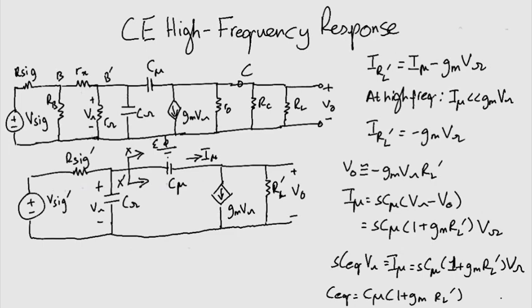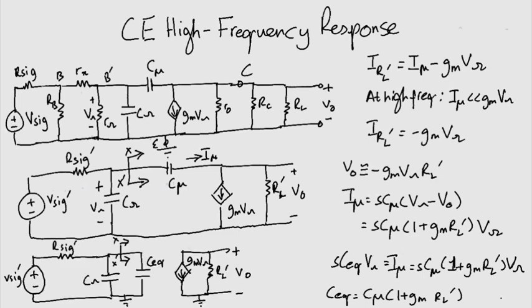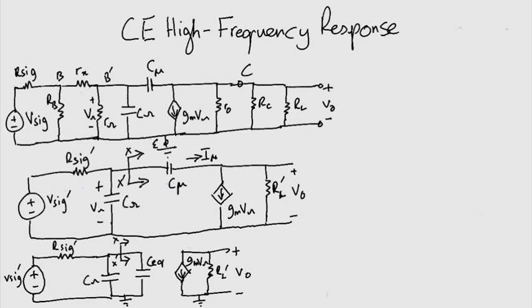Now let me show you how this further simplifies our circuit. Here you go. We have separated our circuit into two parts. This makes our derivations very easy. Using C equivalent enables us to simplify the equivalent circuit at the input side to that shown in your figure. Now we can use this simplified diagram and see that the input side is a single time constant, STC, network of the low pass type. To read and understand further on this, there is a link in the instructor's notes, and you can go and see the different single time constant networks.